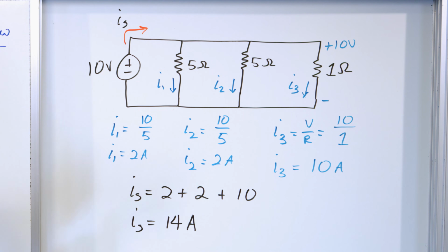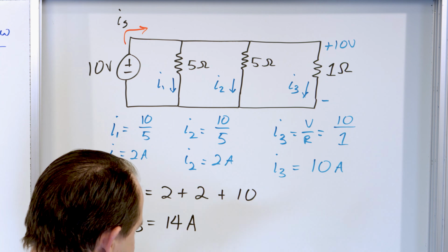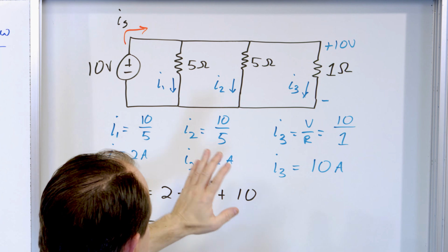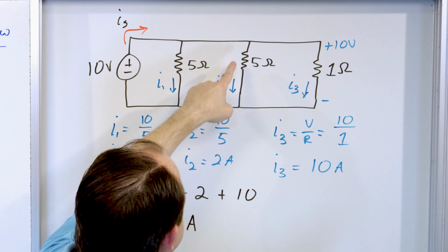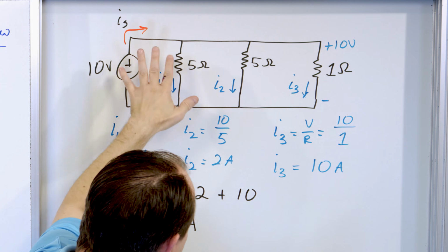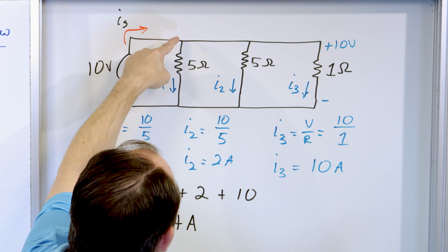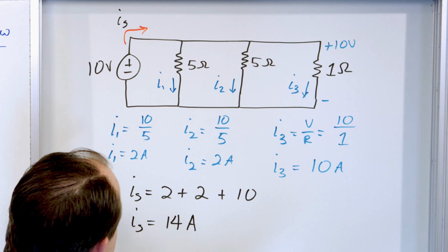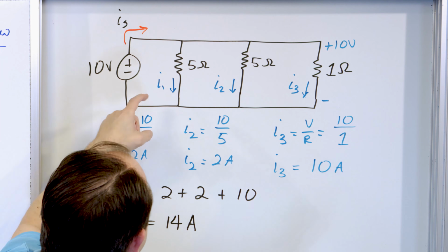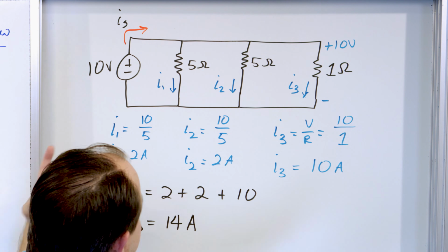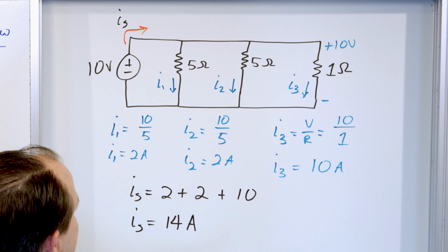So that was the last thing I wanted to talk to you and make sure you understand about parallel circuits. If I remove this bulb, then these bulbs continue, if they're light bulbs, they continue to be illuminated. If I remove this one, then the current is still flowing here, so they're still illuminated. If I remove both of them, then the current is still flowing through there, so it's illuminated. So they all remain illuminated.